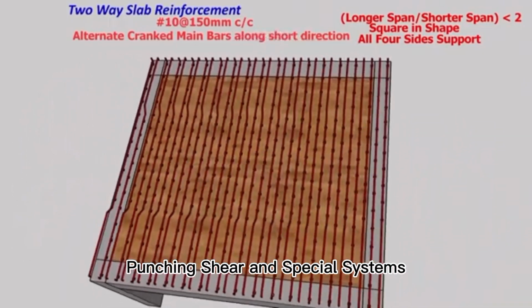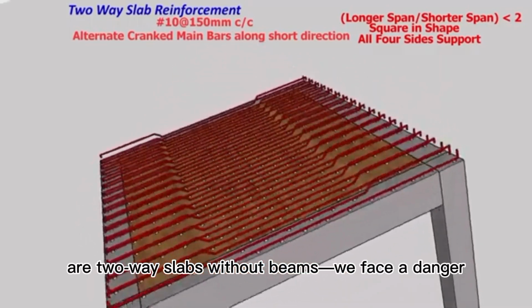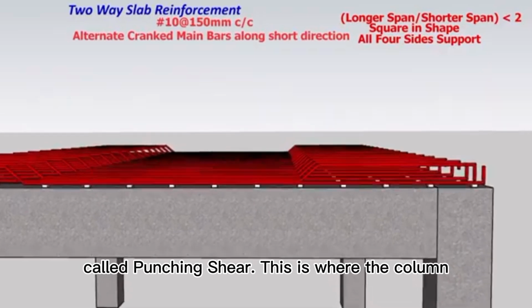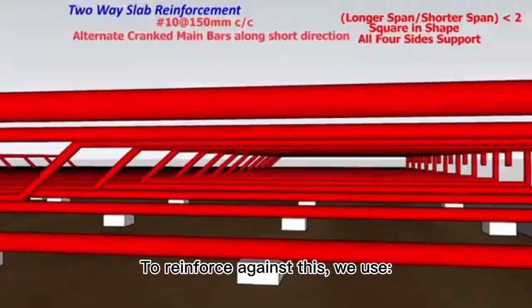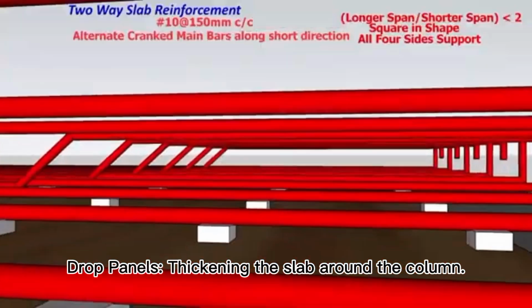Punching shear and special systems. In flat slabs, which are two-way slabs without beams, we face a danger called punching shear. This is where the column could punch through the slab, like a nail through cardboard. To reinforce against this, we use drop panels, thickening the slab around the column.